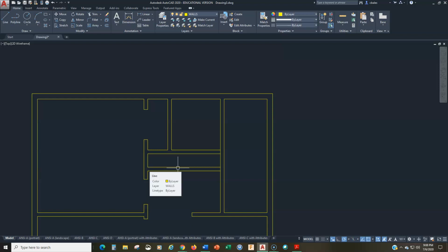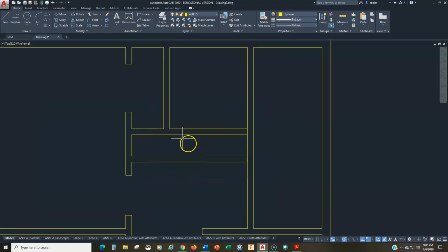Okay. So let's finish this hall bath right here. The width of the hall bath, the inside, is 4 foot 1/2 inch. So I'm going to offset 4 foot. Now here I need to be careful. Dash 1/2. Okay, dash 1/2, enter. Inside, we go like this. We offset 4.5 inches for our interior wall.